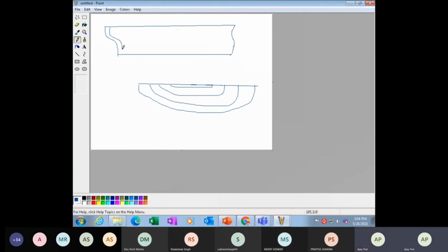And we're making the shear plan like this. You can't make a body plan on the shear plan, but you can make a half breadth plan on the shear plan. So suppose you make a shear plan like this, I can make the body plan here on this also, like this. So I can superimpose the body plan on the shear plan.